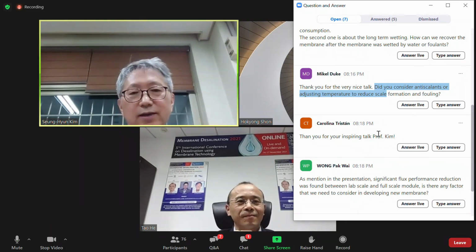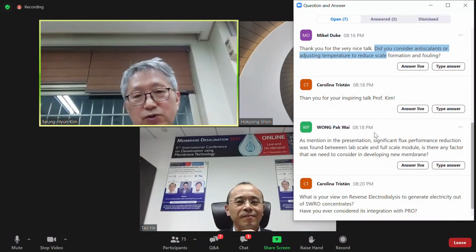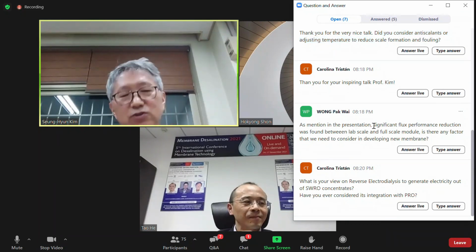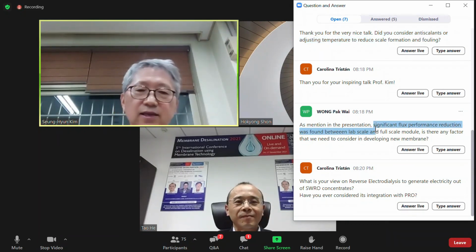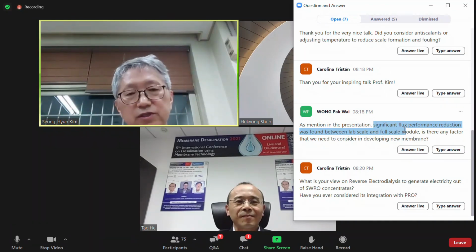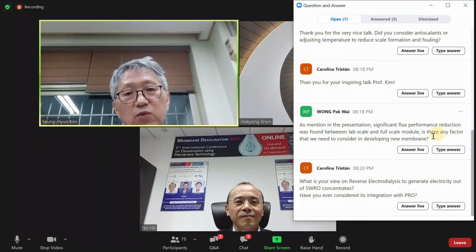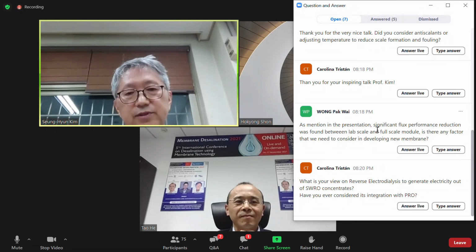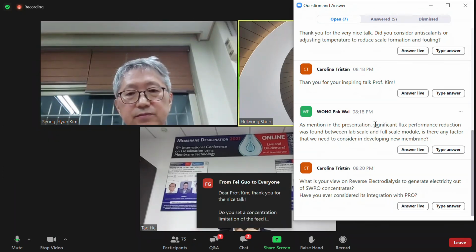Well, actually, for this pilot plant study I showed you, I didn't add an anti-scalant. This one is because I like to see the scaling. That's the reason I did not add anti-scalant. But for another pilot sent to Saudi Arabia for 6-month operation, definitely I need to add anti-scalant. Without anti-scalant, even in 3 or 4 days of operation, you see scale formation.